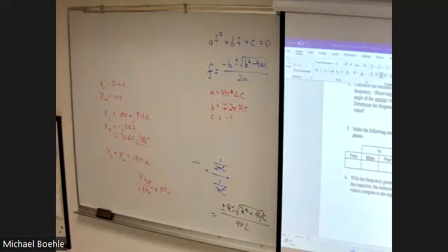And check the phase angle. Phase angle should be close. You know, if you're off a little bit, it doesn't take much of a not quite exactly zero reactance to make that. When you're working with 100 ohms, if you're off by 100, that's a 45 reactance. So depending on how good you get it, see how close you get. To find the perfect resonance, it might even be better to look across XL and XC. Find that 0 degree phase. But anyway, so that's what you're going to see initially.